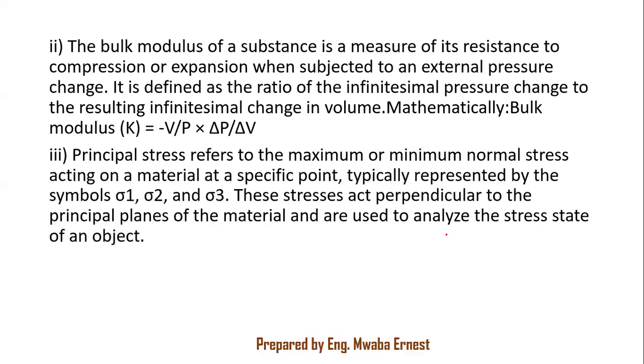Then what about the principal stresses? The principal stresses, there are normally 3. You can have stress 1, stress 2, stress 3, and they refer to the direct stress. You have the maximum, minimum, or we're saying either minimum or maximum normal stress acting on a material at any given point. So you can have stress number 1, 2, or 3, where 1 is the maximum one, 2 the mid, and 3 usually that's the compressive one.